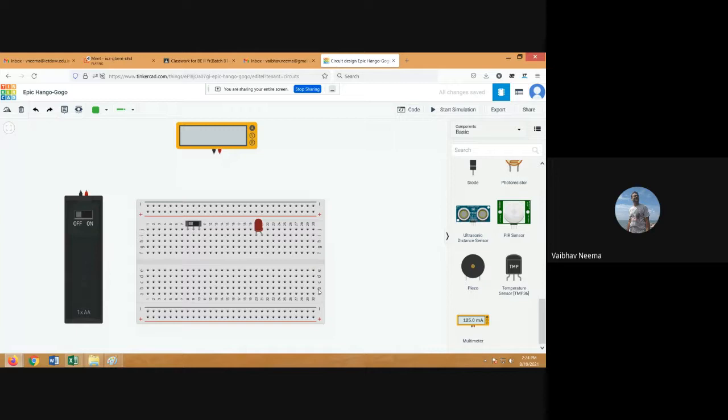Now we'll see the property of this breadboard. If I put any voltage onto one part of this horizontal line, then all these connections get shorted. Short means they have the same potential. Generally we use this line to get the power supply, so we connect it with the power supply. All these dots will have the same potential, which means you will get the high voltage, the 5 volts.